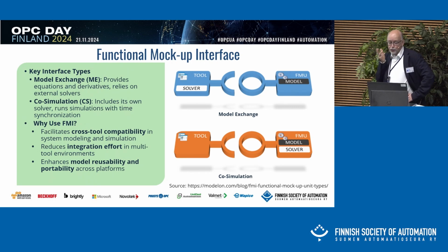And so this cross-tool capability is good, and then the integration and reusability is also this portability. We found out during the testing, which was part of the virtual sea trial project with Meyer, Kone, Wärtsilä, and Semantum also there, that we were testing the different FMUs and found that sometimes the FMU doesn't contain all the needed runtime libraries, so some libraries were missing. We found those and solved the problems, and then we got the different FMUs running.